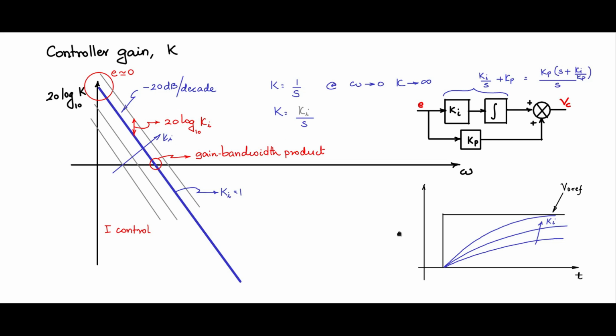This is an integrator, the integrator that continues to stay. There is a zero at some frequency point on this x-axis, Ki by Kp. Now let us say at some point I design and place this as Ki by Kp. So at this Ki by Kp value of frequency, I place the zero. So what should happen? The pole is giving minus 20 dB per decade, the zero will give plus 20 dB per decade.